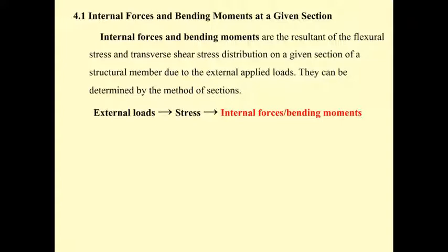By cutting the beam or the frame at a given section, the internal forces and the bending moment also can be determined from the equation of equilibrium by using the state of equilibrium of that portion of the beam or the frame.